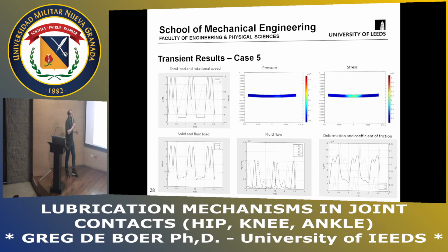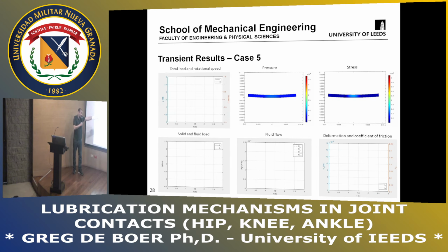But what's really interesting here is that, again, if you look at the 2 colourful images, you'll see that the pressure changes really, really quickly, whereas the stress changes slowly, and it is only in this region where it is constant that the stress actually starts to relax down towards 0. And you can see that in this graph here.